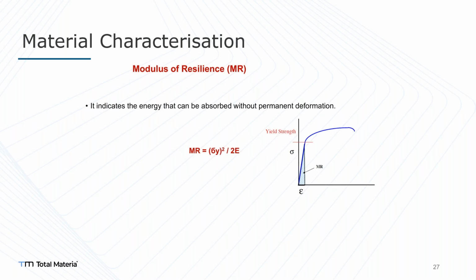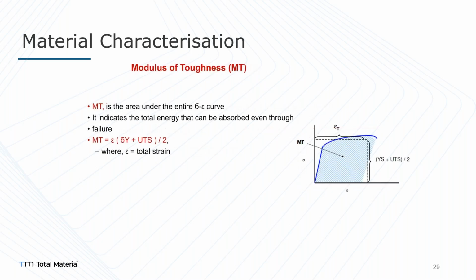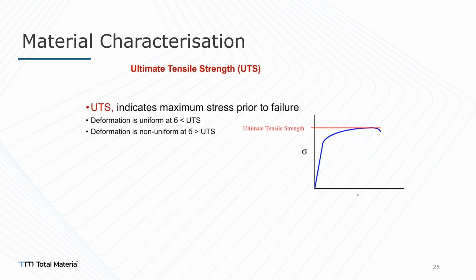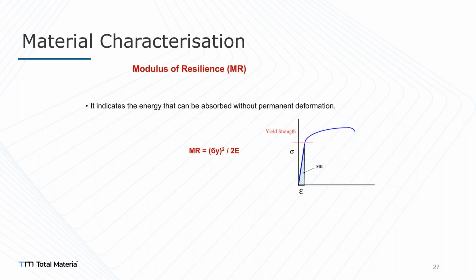About crashworthiness, in my thesis or my work, what I've seen is that in the linear elastic region you see normal behavior, but when you increase the displacement, certain local collapses happen. With those collapses, you see a softening behavior as well.